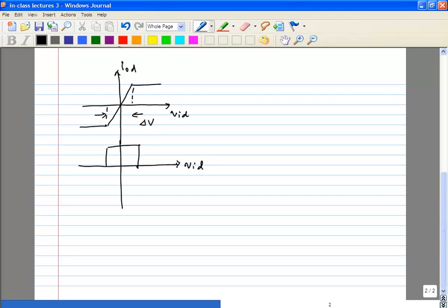Okay, let's plot. This is your Gm as a function of voltage, and this is again delta V. What is this Gm of V? We have a delta V, it's 2 I_T over delta V. That is your Gm of V. So plot versus time, Gm of t. The effective Gm of t of the differential pair is going to look like this.